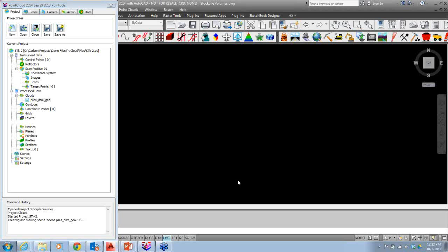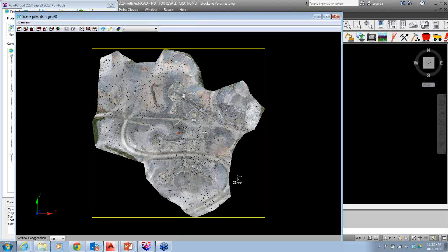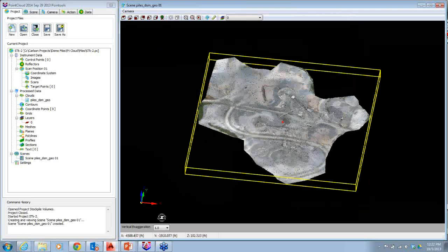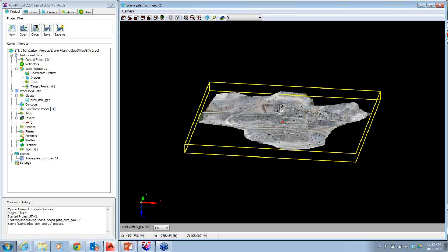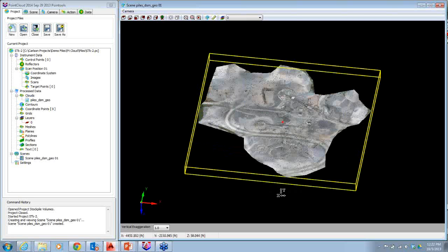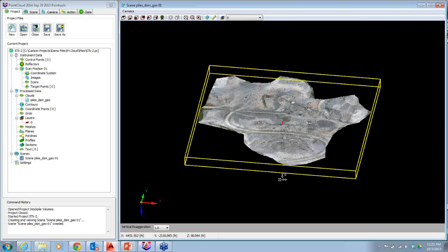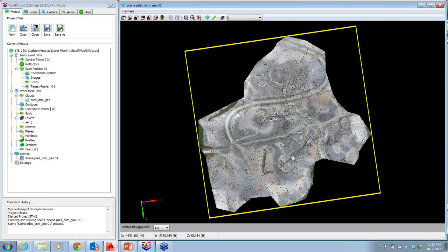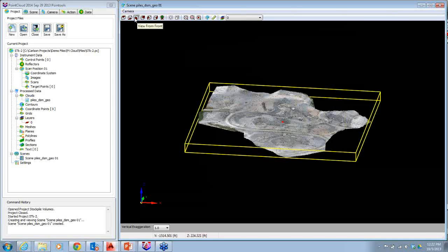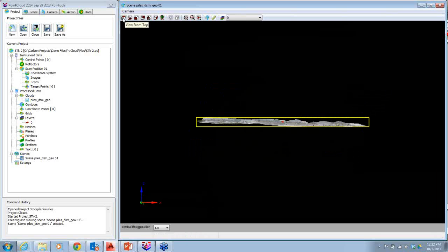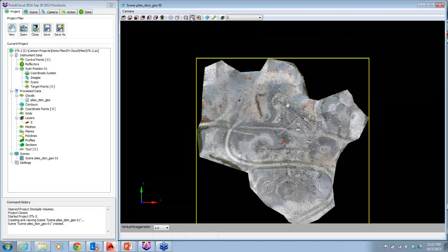And you can see that as I move this up, whenever you're moving, be very careful that the blue z-axis is pointing up. If you go the opposite way, you sometimes think you're actually looking at the site, but the blue is looking down. You're looking from underneath. So I'm going to move this back up again. And if you ever want to get back to where you were before, you can store a home position, or you can just do zoom front, zoom center, and zoom extents.